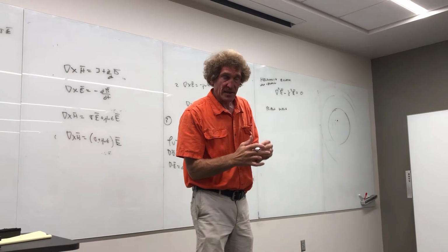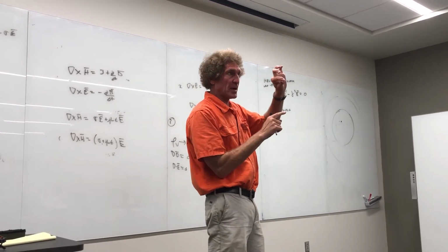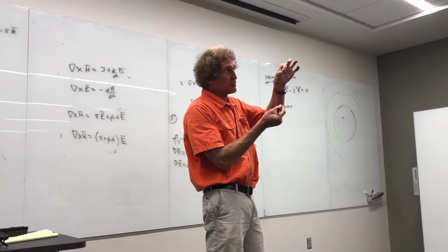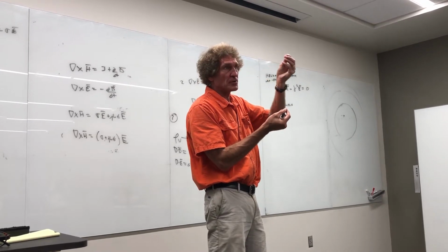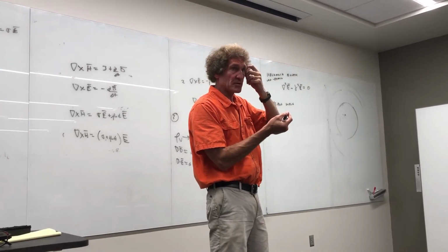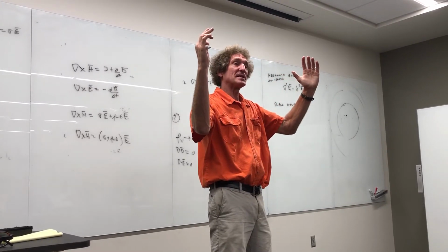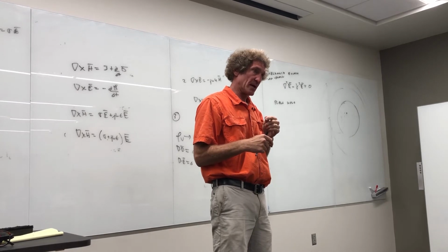And this is unlike the E field on a capacitor. If you charge a capacitor, there's an electrostatic field around the capacitor where all the electrostatic energy is stored. And when you put a resistor across the capacitor, it shorts all the charge on the plates through that resistor and brings the potential down to zero. And what happens is it takes the energy back out of the field and puts it into the resistor, the current going down, all right?